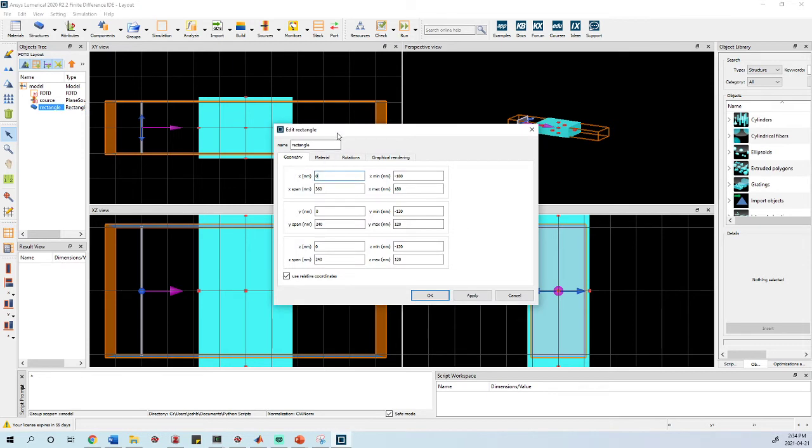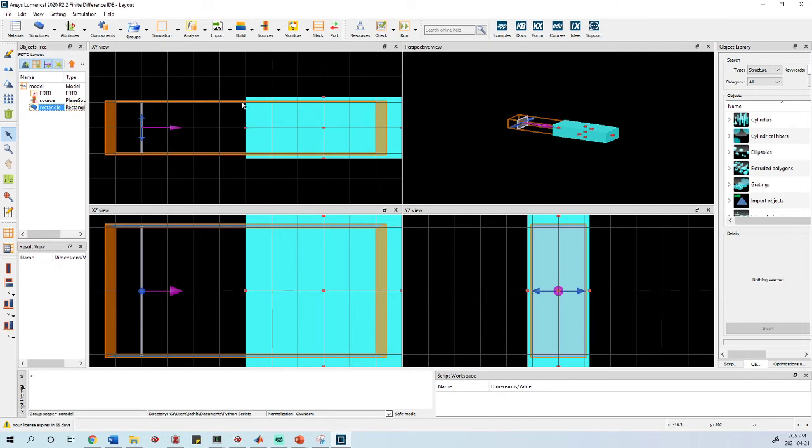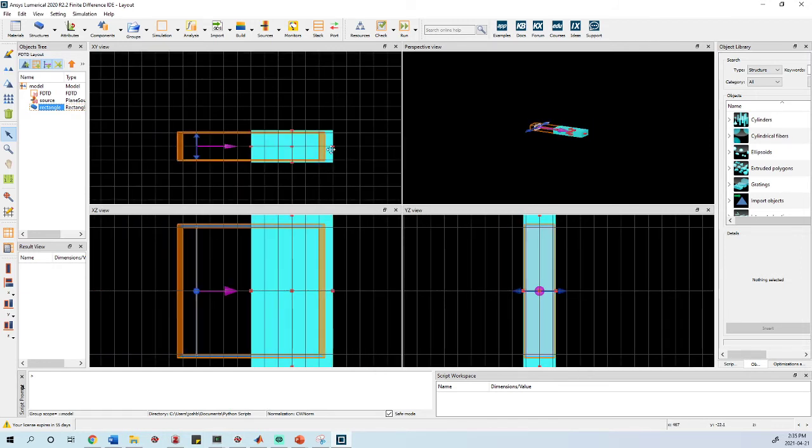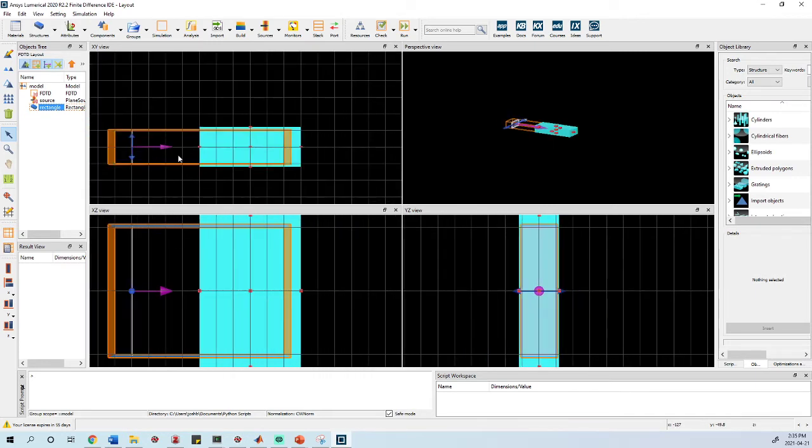All right, as for the X direction, we want it to go off to infinity in this direction. So I'm going to set the X geometry using the X min and X max. I'm going to set the X min to be 0. So that means that the top end here will be halfway through the simulation. And I'm going to set X max to be 600 nanometers. So apply that. So here we go. It starts off halfway through our simulation domain and it sticks out again, which again, is not a problem. The simulation will cut that off for us.